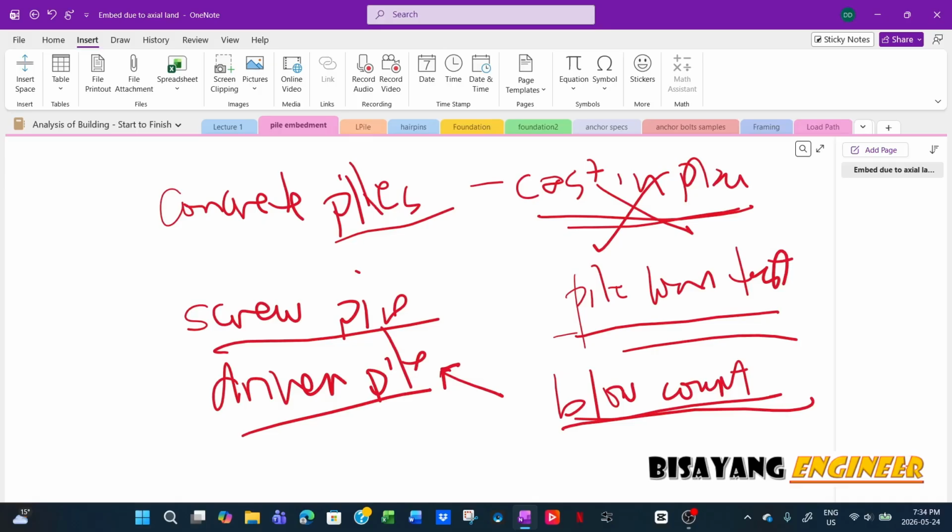So for our projects before, sometimes the depth or the pile embedment is ridiculous, say you're already up to 60 feet, and you still don't achieve the refusal. So they would ask me, are these blow counts okay for this pile? The length is really deep now. That's why I don't really specify a driving criteria of drive to refusal. I always provide a minimum blow count.